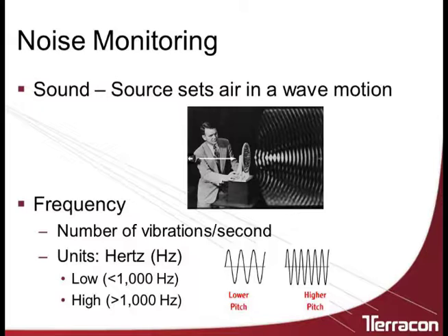And you have those frequencies that are high frequency, which are greater than 1,000 hertz. And these typically are shorter wave patterns. They're easier to control, so you can control them with sound barriers, other materials in order to reduce that noise level.